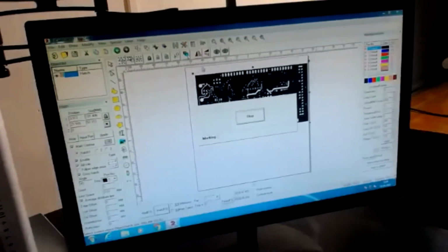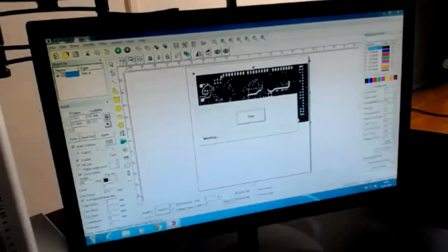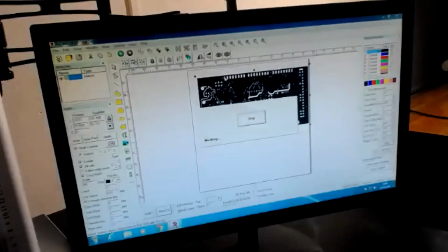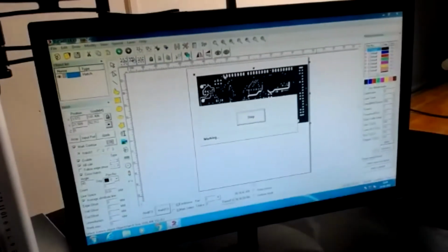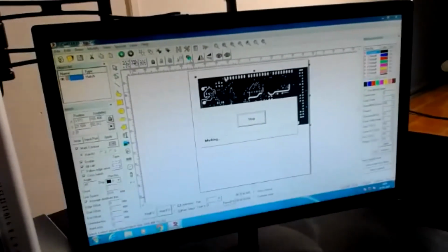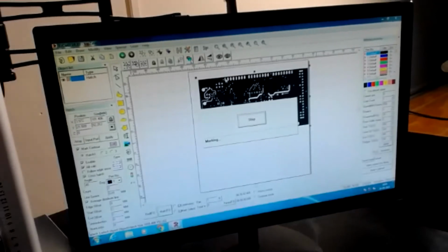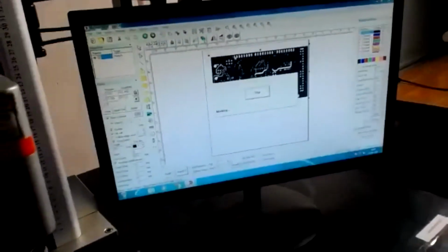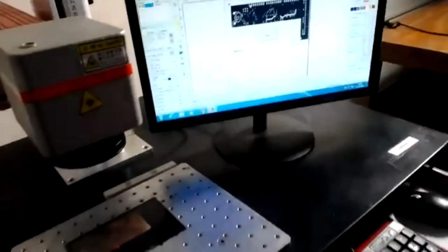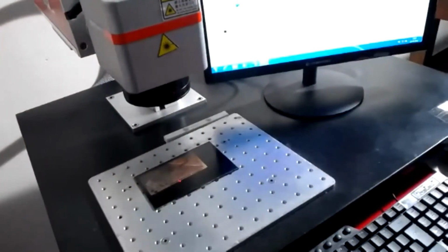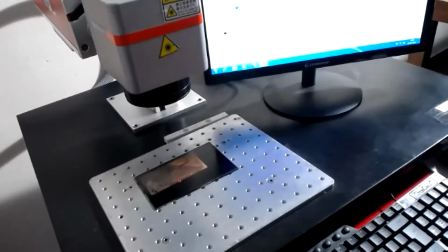A very similar process you have to do for drilling also, because when you do the drilling process, laser drilling will be much more accurate as compared to CNC drilling. So most often I will do the drilling process with laser only. The laser will do any type of drilling. For example, some vias will be 0.3 mm, some vias will be 0.5 mm, some vias will be 1 mm, some vias will be 3 mm. Even for corner vias, you can go up to 3 mm. That is as per the design rules we can go.